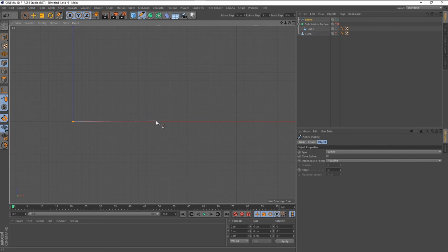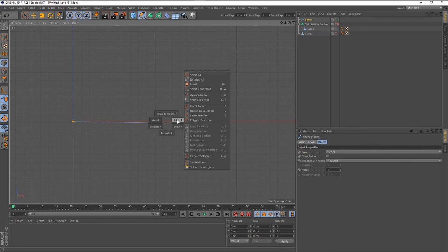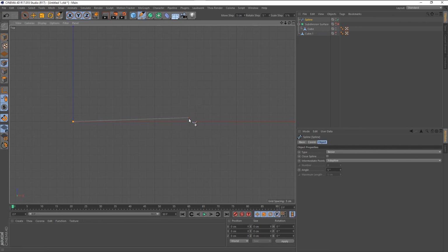Another way to do it, I think, is V select, V snap. You can set them in there. You hit V and then you can go into these. So I've set all my snaps to be on, intersection snap, midpoint snap, all of those on. So all of those are enabled. But quantizing is not enabled, and you can see that it's not going on the axis.